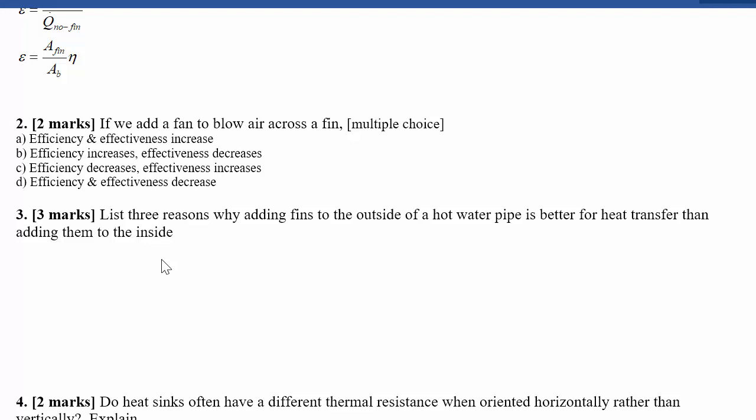Right. So a similar reason to that second one there is because the convection is lower on the outside, the fins are going to be more effective there. If you have really strong convection, like you would in forced fluid flow, compared to maybe on the outside you would have free airflow. So free airflow on the outside is going to have a much lower convection coefficient, which means that the fins would be able to, with a reasonable conductivity, stay at a very high efficiency, and that's going to make them more effective compared to not having the fins.